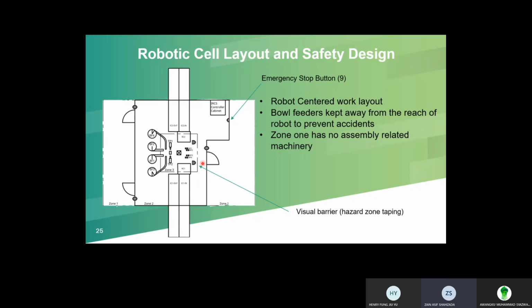For zone 2, there is the IRC5 controller cabinet that is responsible for the robot to work, and it is placed in zone 2. Mostly the replenishable feeders are inside the zone 2 area, like the magazine feeders and the tape feeders and the drum bringing everything in. The entire zone 2 is enveloped by a physical barrier, which might be a mesh gate with entry gates located at 3 points.